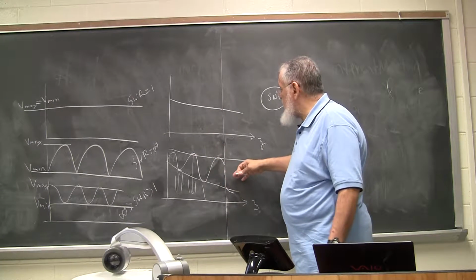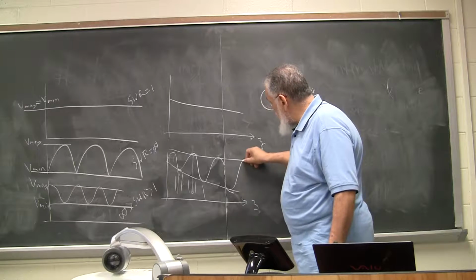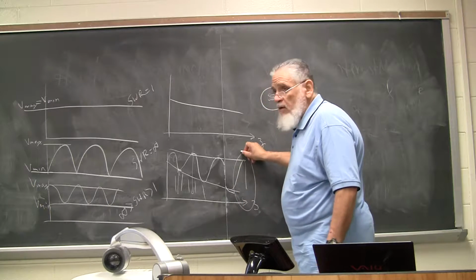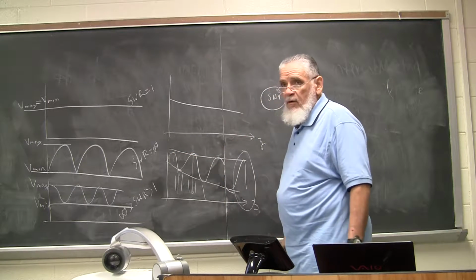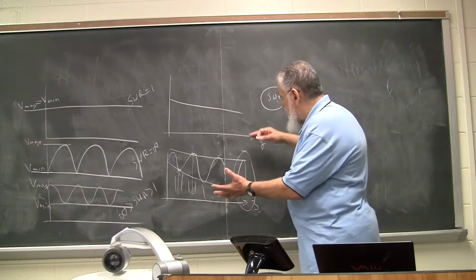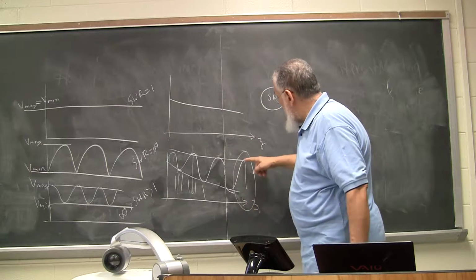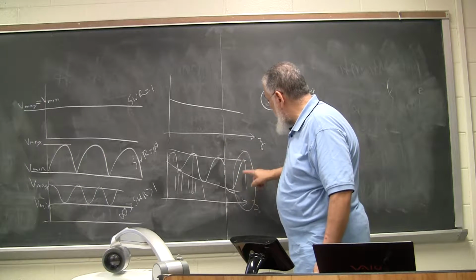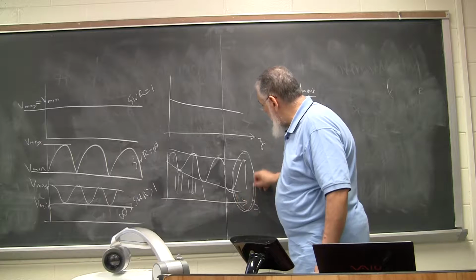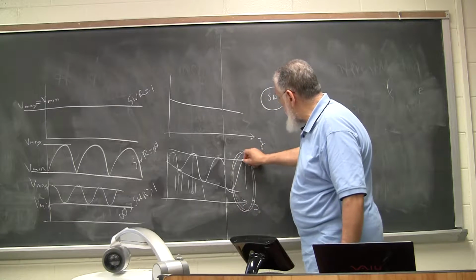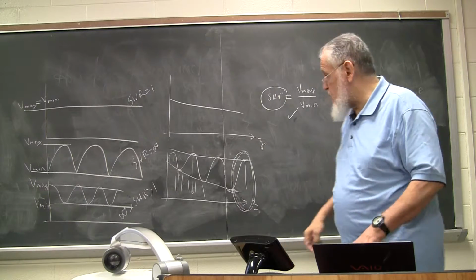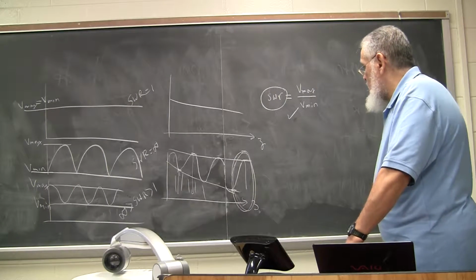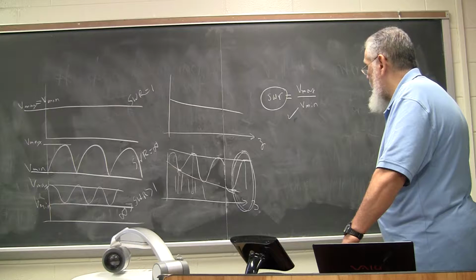And the definition of SWR is typically given close to the load, right there. Right? With the loss, the way you see things here, the SWR is a much better number. Right? The curves shrink, and the ratio here is at maximum close to the load, and that's where we define the SWR typically. You take the first max and the first min, and people would realize that this is really the worst case that you can have, the standing wave ratio.